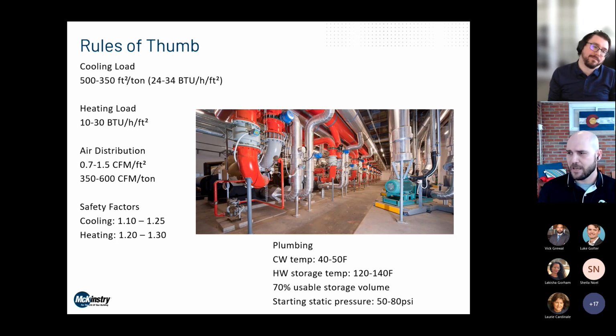And then on the plumbing side, standard domestic cold water temps are in the 40 to 50 range. Maybe you don't get quite that cold in Florida or some other parts of the country, but that's pretty standard for a lot of places. And domestic hot water storage temp is in the 120 to 140 range.